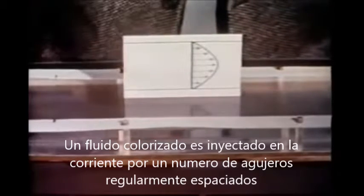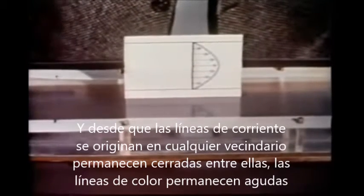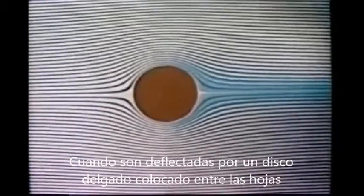In the Healy-Shaw apparatus, colored fluid is injected into the stream through a number of regularly spaced holes, and since the streamlines originating in any neighborhood remain close to one another, the lines of color remain sharp. When they are deflected by a thin disc placed between the sheets, they assume the same form as those of an ideal fluid when deflected by a cylinder of the same cross-section.